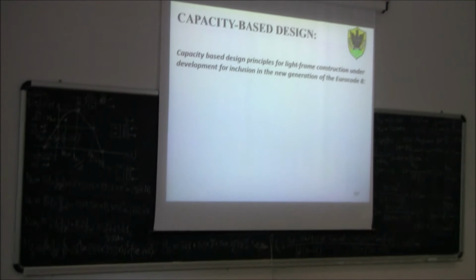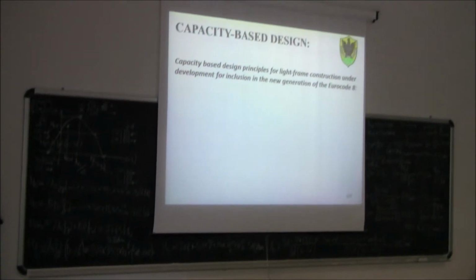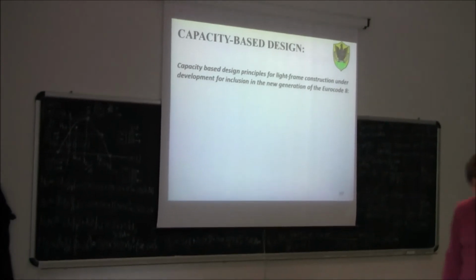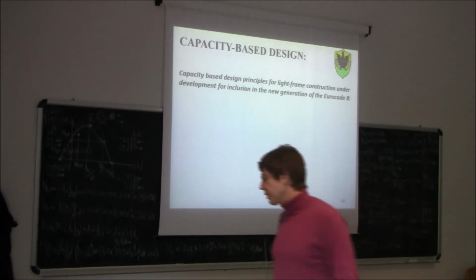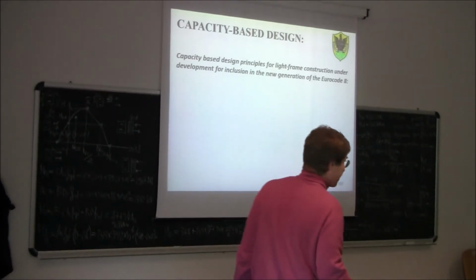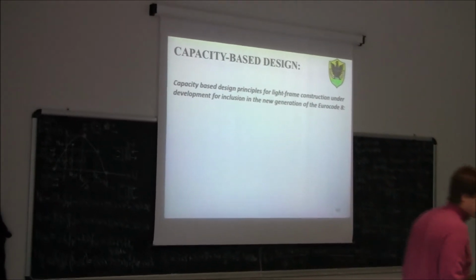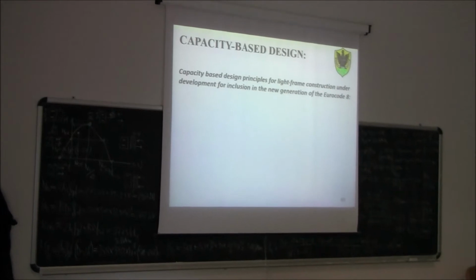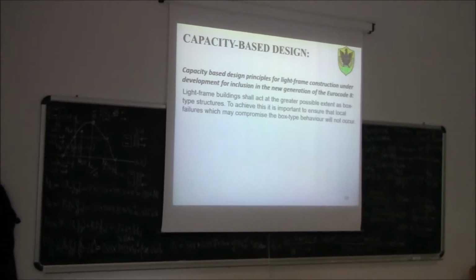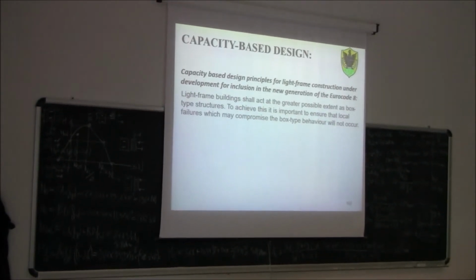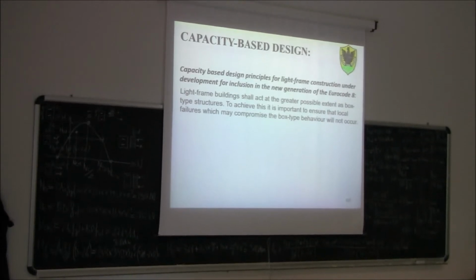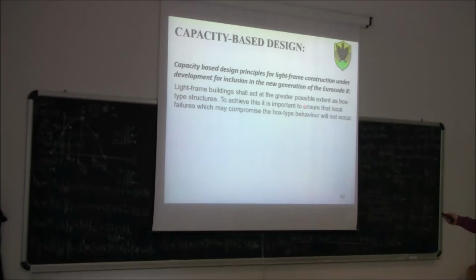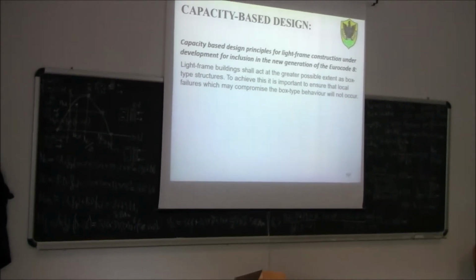Lifetime buildings. If you remember, last time we discussed extensively the seismic design of timber structures, capacity-based design of light frame, and capacity-based design of cross-laminated timber. Today we want to see what the provisions are if you want to do a capacity-based design of a light frame building. Also for a light frame building, we need to design it in such a way that it will act to the greatest possible extent as a box type structure.